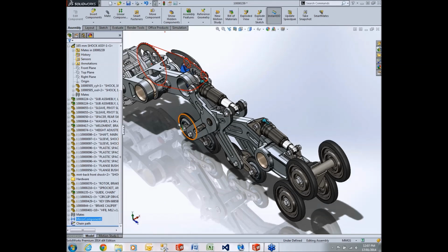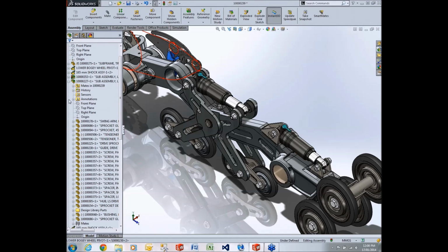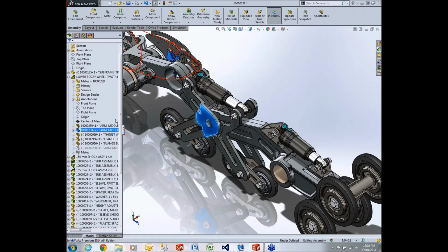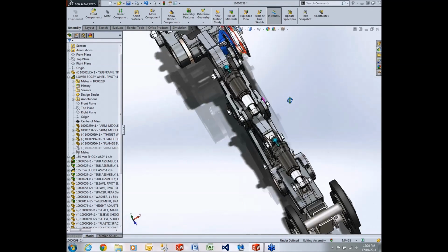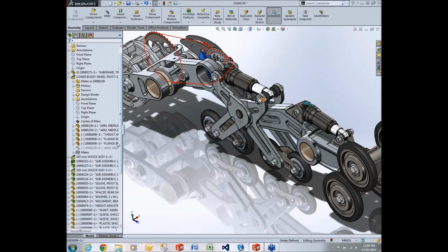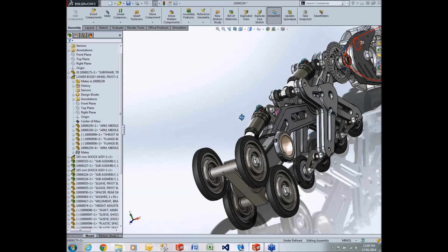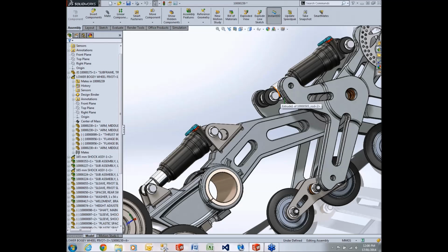However, there has been a bit of an issue if you've got asymmetric sub-assemblies like this scissor that we've got here. So I'm going to go back up to this scissor assembly and unsuppress a component. You can see at the moment we've got this mirrored correctly to the other side. But if I unsuppress this extra component on this side here, because the center of mass moves, the mirror is now incorrect. We can see it's not lining up correctly with these bolts.